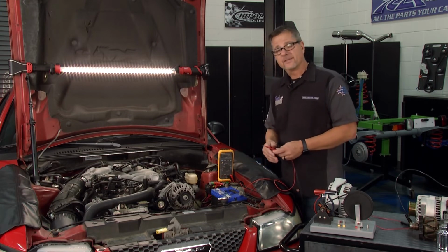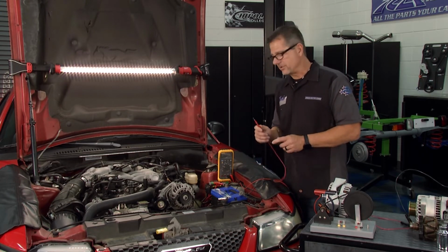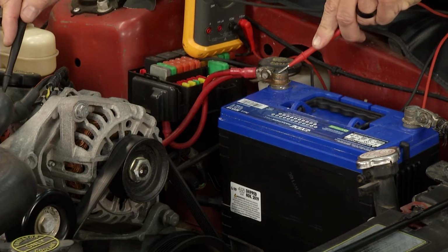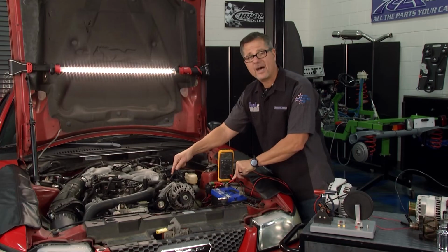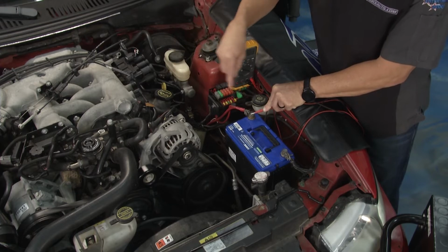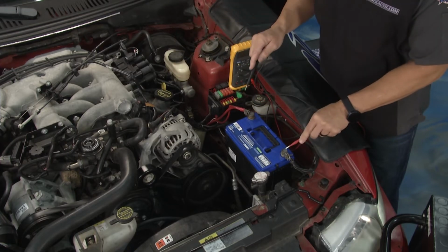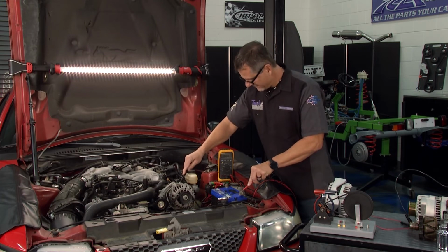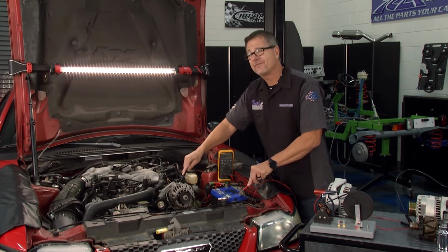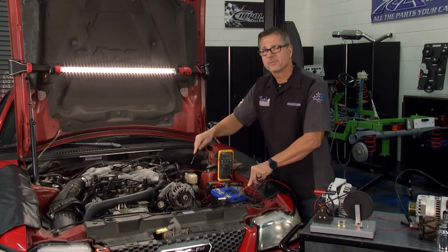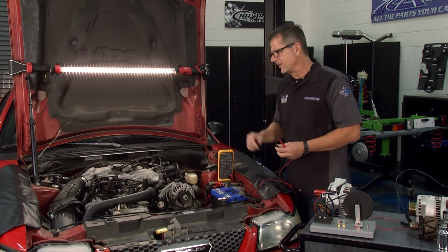Once the car's running, then I'm going to check for voltage drop. This is hugely important. I can come here on the positive cable, and I can go over here to the positive. Positive to positive. We should see less than 5/10 of a volt, a half of a volt. If you have more than that, you're getting some loss in the feedback to the battery. And then I'm going to switch from negative to the case, negative to negative. And we're wanting to see a low voltage as well, less than half of a volt, because you have some loss in the ground system. Not good. It's going to prematurely wear out your alternator, and we don't need to do that.